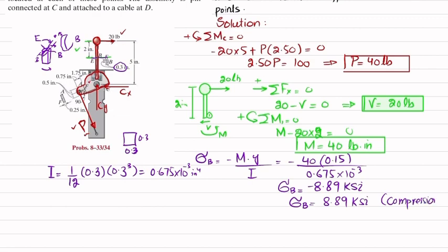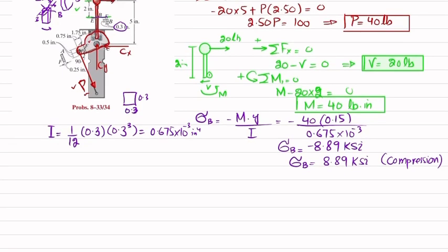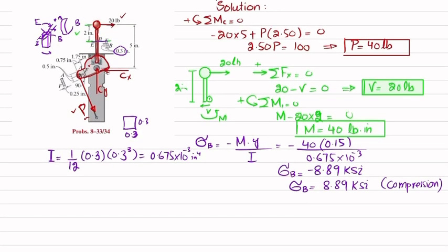Okay. Now we will move toward our second part. Since you can see this was your point E and this was your point B, and this was the neutral axis. So we know that shear stress is equal to V into Q, since point is B, so VB QB divided by I into T. And Q, we know that QB is equal to y bar dash into A dash.